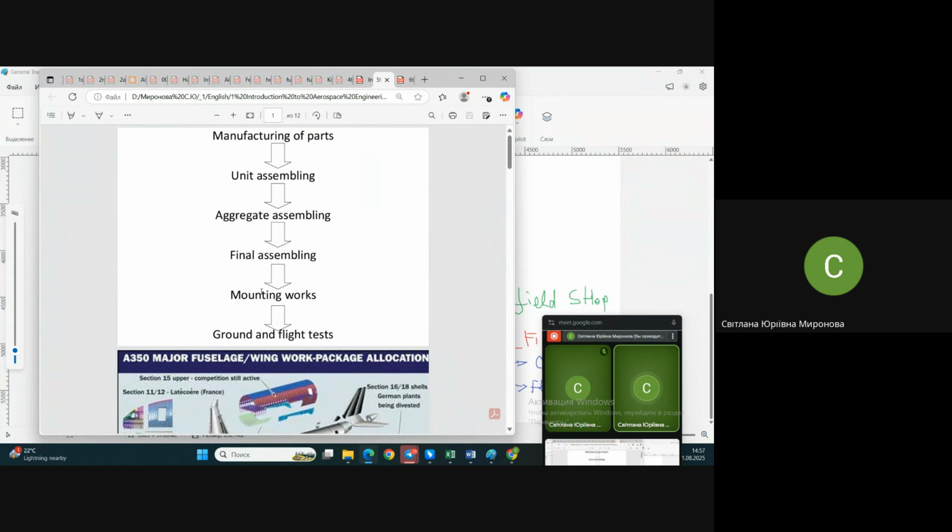Technological efficiency of structure is the complex of properties that reflect conveniency of structure for manufacturing in terms of saving material resources, labor resources, time and money for manufacturing and pre-production. In English-speaking countries, they have such nouns written with dashes: design-for-manufacturing, DFM, design for assembling, DFA, design for maintenance.